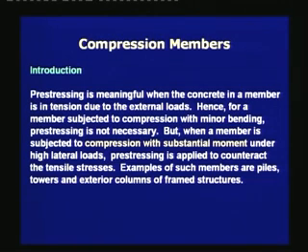Prestressing is meaningful when the concrete in a member is in tension due to the external loads. Hence, for a member subjected to compression with minor bending, prestressing is not necessary. But when a member is subjected to compression with substantial moment under higher loads, prestressing is applied to counteract the tensile stresses. Examples of such members are piles, towers, and exterior columns of framed structures.